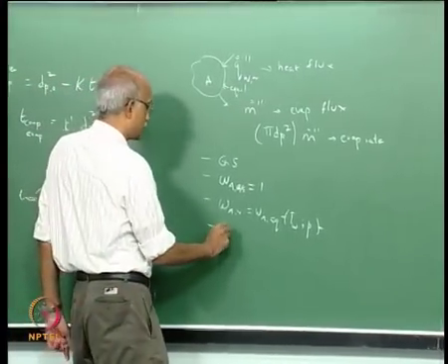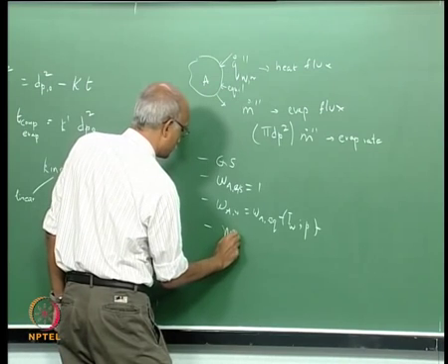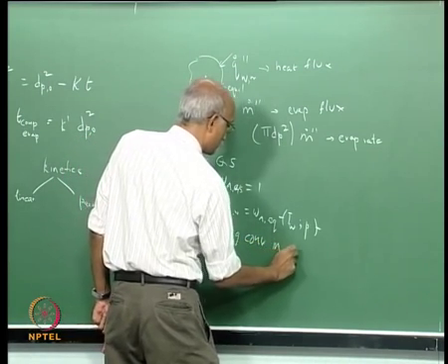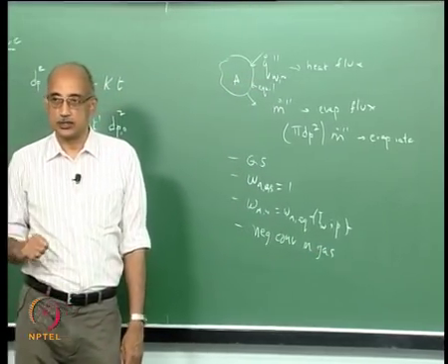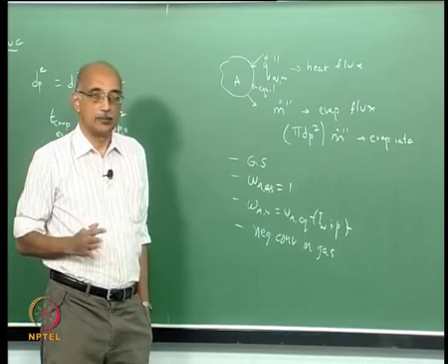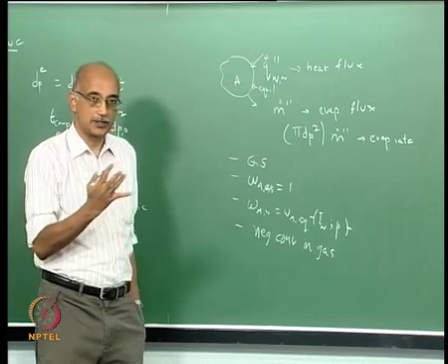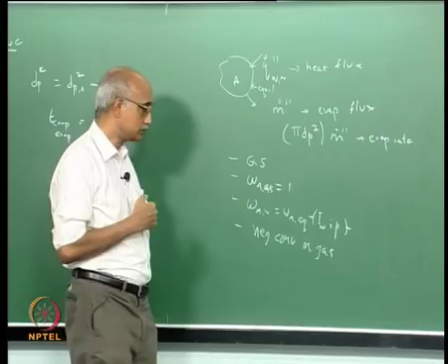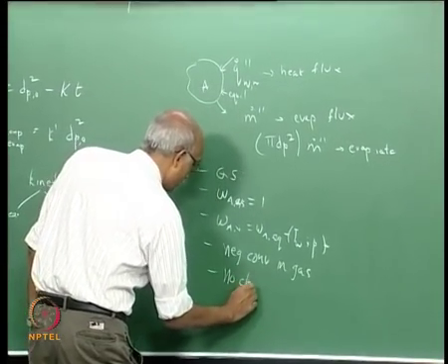Let us assume that the surrounding gas has negligible convection. That is both natural convection as well as forced convection are relatively low in magnitude. Therefore, the combustion process or the burning process is essentially controlled by diffusive phenomena. Let us also assume that there are no chemical reactions in the gas phase.